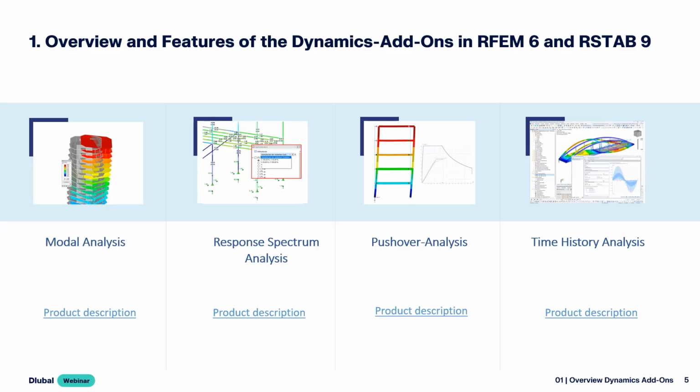The second part is, well, it also puts the demand into place in form of the response spectrum, and this is related to a single degree of freedom system. Quite handsome that we already made the pushover analysis, which gave us this single degree of freedom system behavior of our multi-degree of freedom system with some transformation. So we can compare demand against capacity, and then we know where we are at.